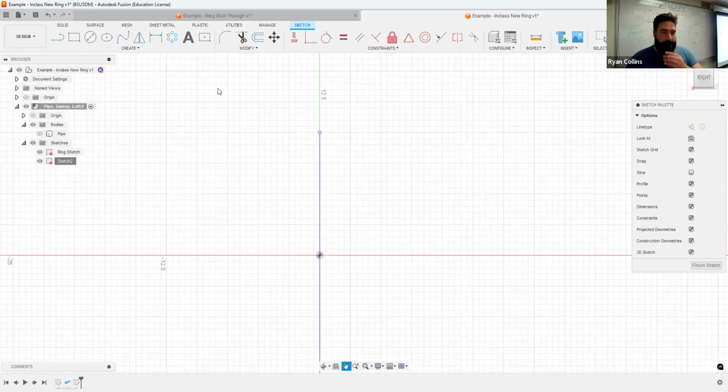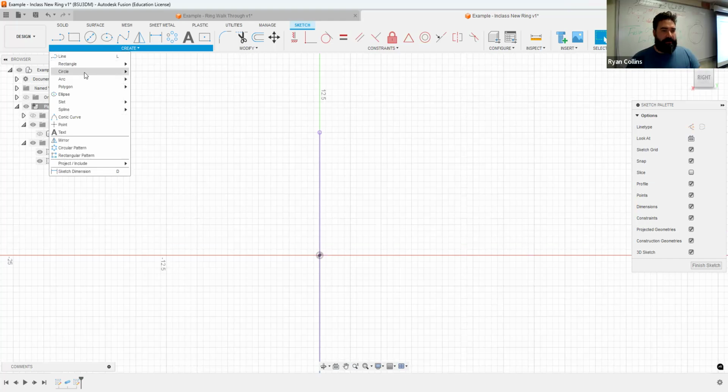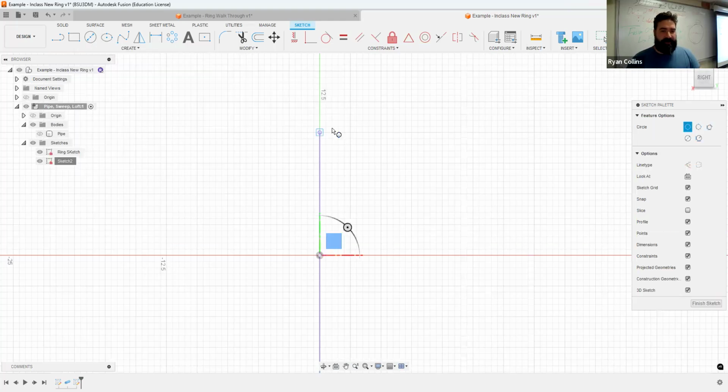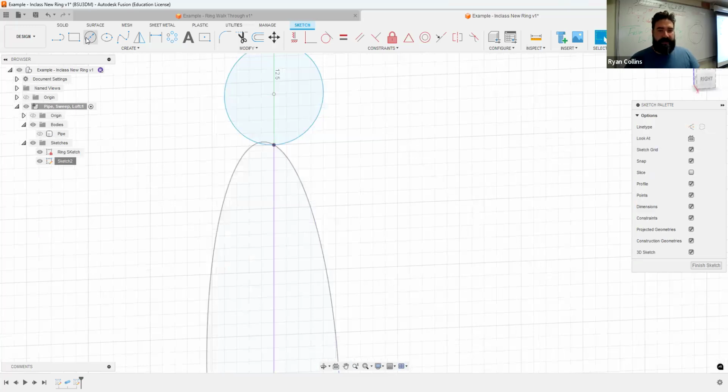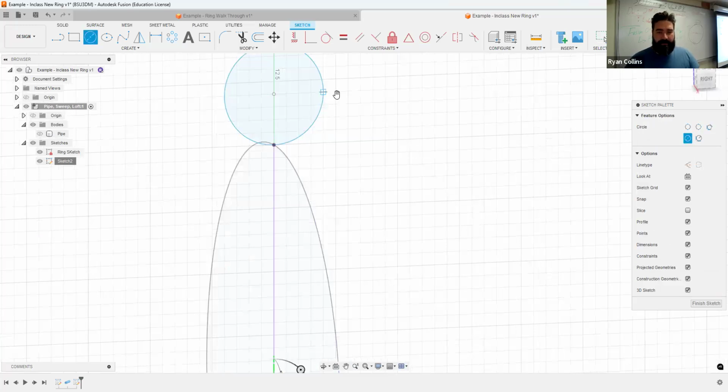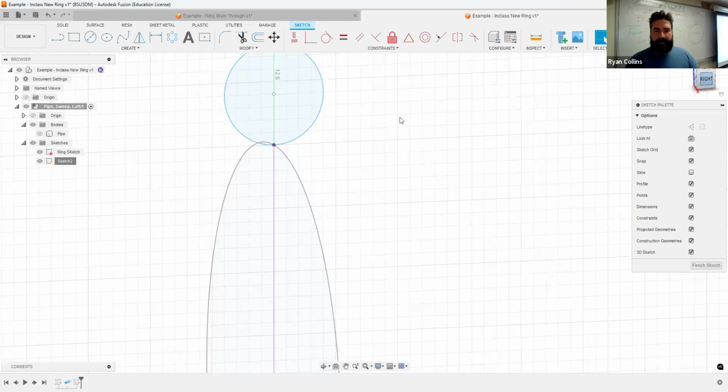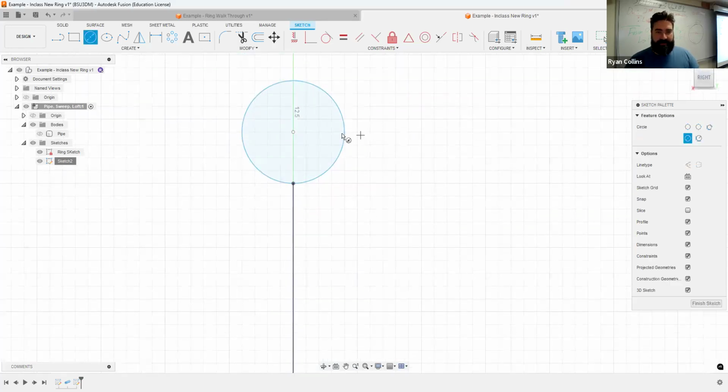All right. So from there, let's say 2-point circle. I can start at the very top and go upward, I don't know, 4 millimeters. Great, sure. Now, if I left it just as that, it would simply be a circle and basically create the same thing as a pipe. But let's add a little bit more to that. Let's say a knobbly bit here, 2 millimeter. Oops, it switched planes on me. Make sure you stay in the same plane, otherwise it gets really screwy. Sure, 2 millimeters right there. I'm just adding things. That's all.